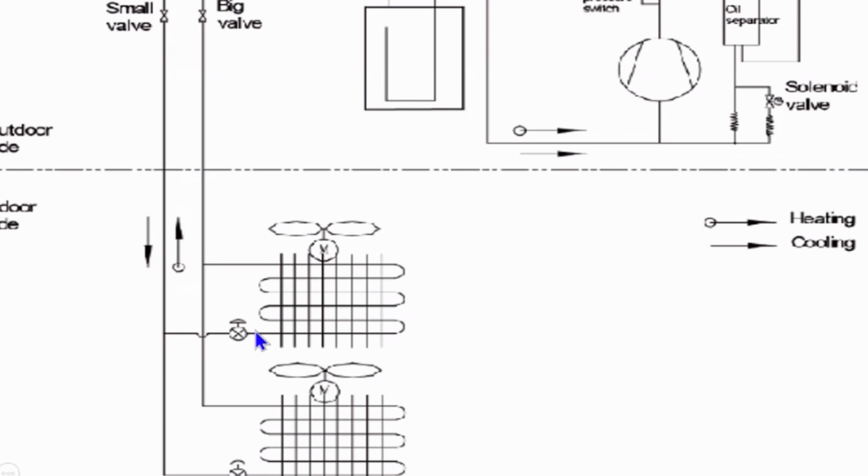Yep. Then as the refrigerant travels through the coil and absorbs heat into the coil, our leaving thermistor should be significantly warmer than our inlet, right? Oh, yeah. That's the data that I keep telling you guys the service tool will answer for you. So if you've got 4 heads, look at the data on each coil.